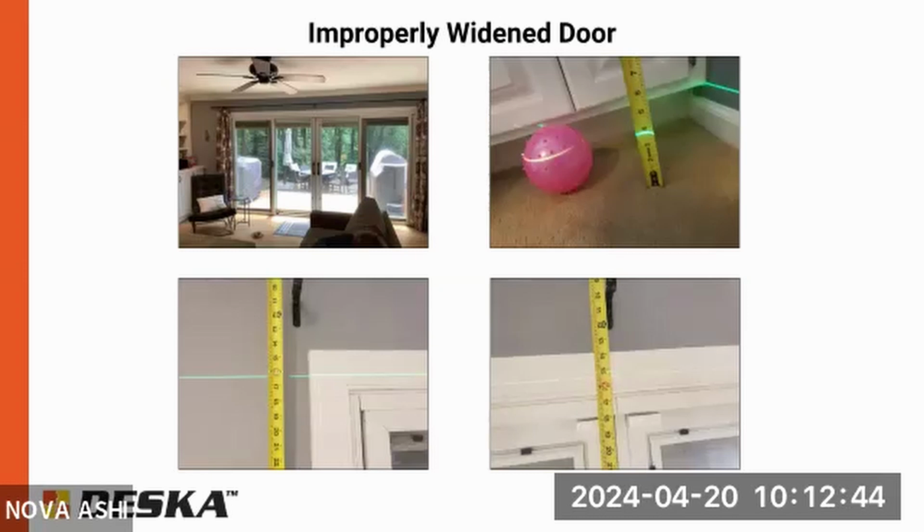Here's another similar example. In this case, the owner had a 12-foot wide door. This is out in Reston. And he thought the door was sagging a little bit. The door wouldn't open all that well. So we came out there and we observed that. We put a laser on it. We could see how it sagged down in the middle. We went upstairs above this, and the floor above sloped about 1.5 inches towards the same area. So we're seeing multiple signs, multiple symptoms of the same issue.